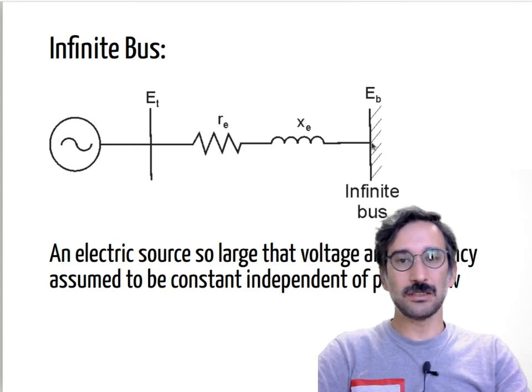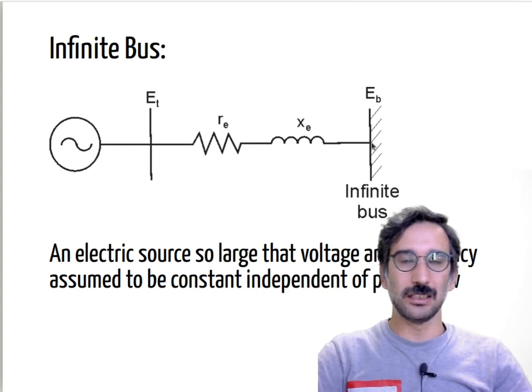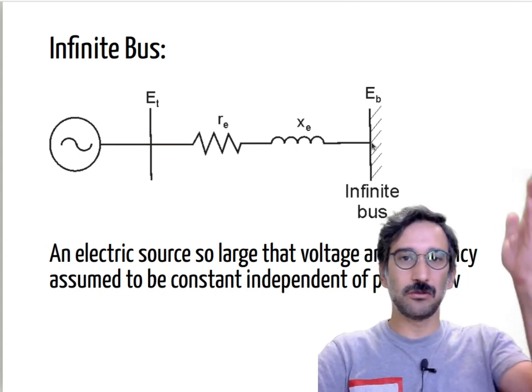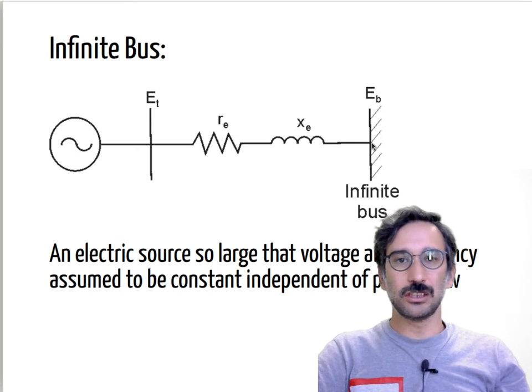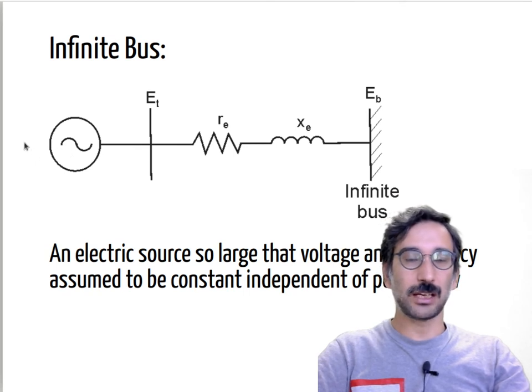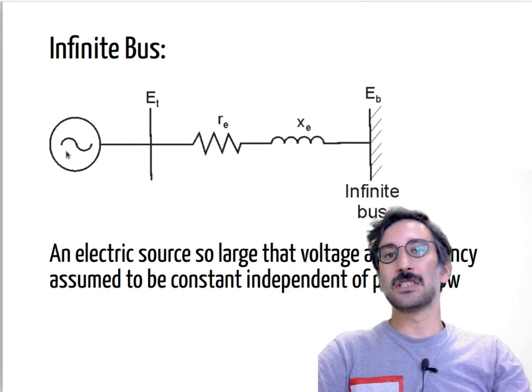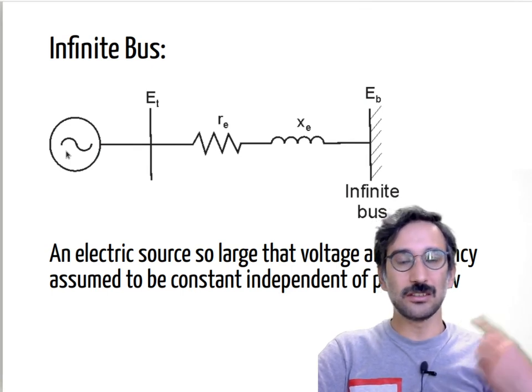So what happens, for example, if you have a hydroelectric power station, and you cut off the water, and you are still connected? If you don't send enough mechanical power through the generator, then your system becomes a motor and will start rotating it.